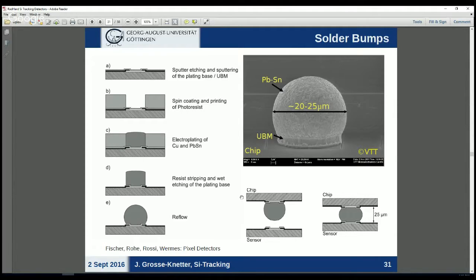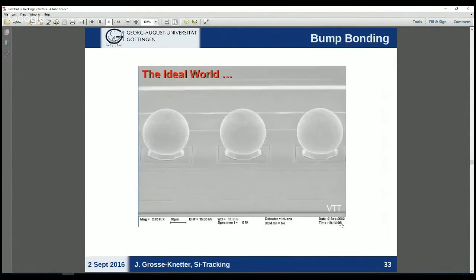So the last part is what I call flip chip. You take that chip, so say the readout chip, flip it over and move it over the sensor chip, which also gets some extra metal layers on top of its pixel contact. You push it on top and again do a reflow. That means put it in an oven, heat up the solder, and you will get electric connection. And that over several rows and columns one by one. That's the benefit. Okay, well, maybe skip indium.